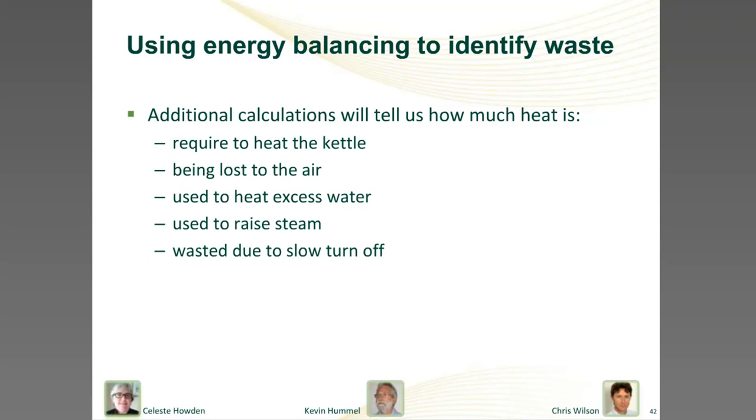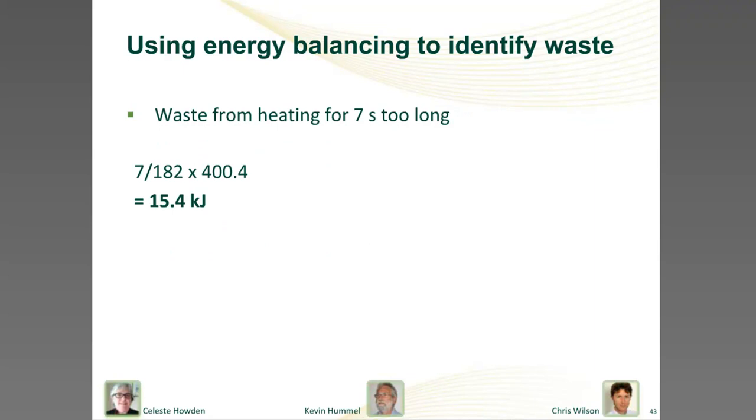There's waste from actually boiling the water, which takes a lot of energy, although all we want is liquid water at 100 degrees C. We're not actually after the steam. Also, I boiled a litre of water. Now, if I was only making 1 cup of coffee, I probably only needed 250 mL. So that's a further possible source of waste. We can do some energy balancing calculations around here to work out which is the most significant waste we need to follow through on.